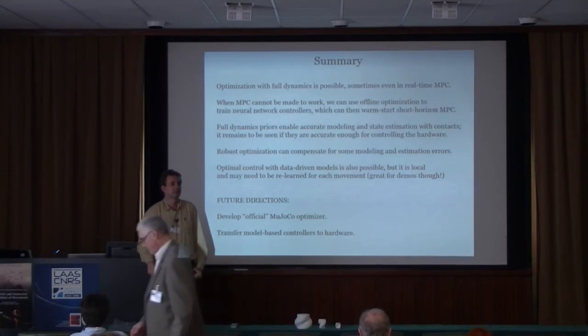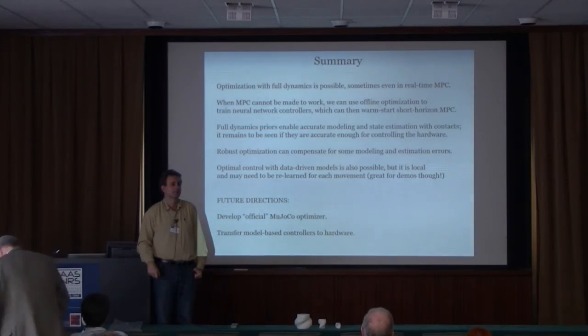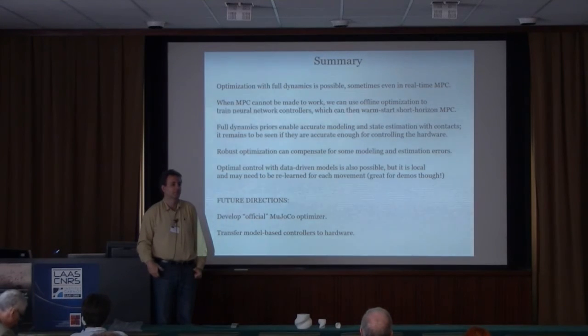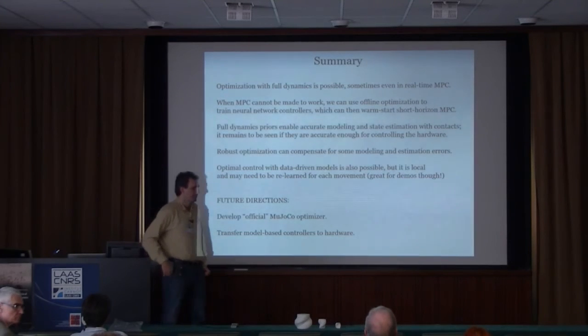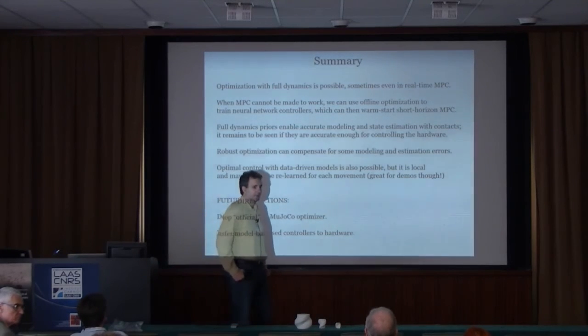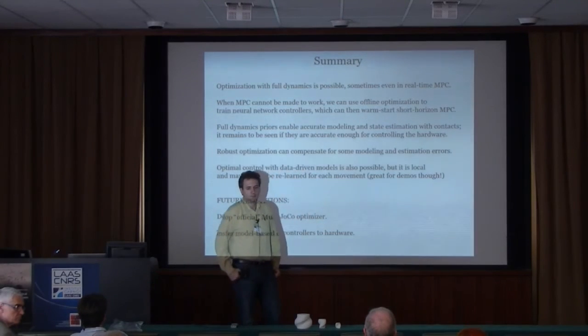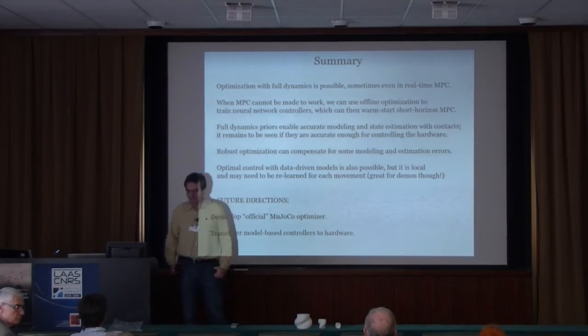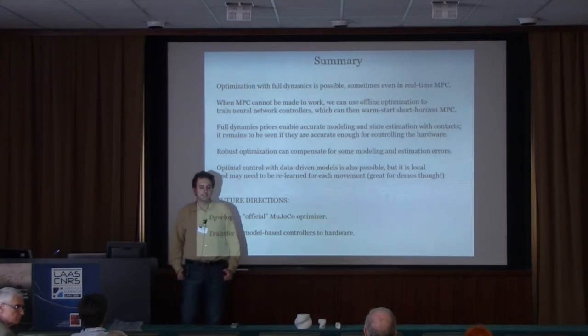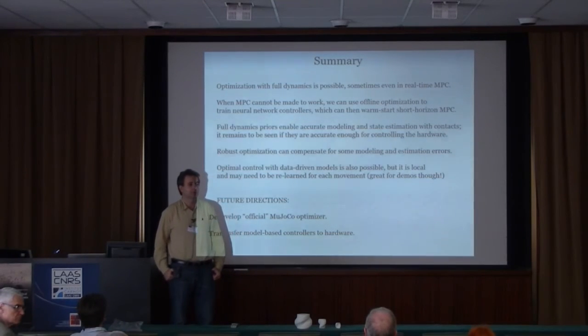I would like to ask a question about the MPC. I think the videos you show are really impressive, and I wonder how much effort you spent on tuning the cost function, because you showed some parameters, but in reality you can also change the sampling on the control horizon. So the control horizon is fixed by your computer. You always use the longest control horizon that you can get away with in real time.